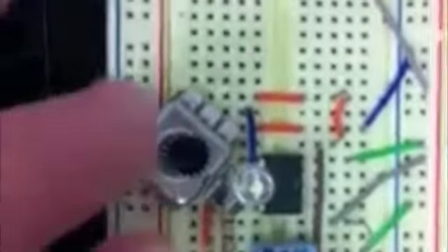Alright, so what we have here is our illumination circuit, and this is our LED that will light up once the capacitor, which has 5 volts, discharges. So what happens is that once it turns to night, the voltage from here will read 4.4 volts with the voltage across, and this will turn on the transistor, and the current and the voltage will pour into this rail right here, as you can see where my finger is.